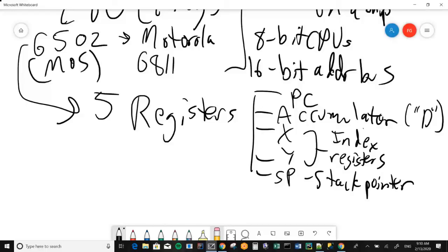When you did the jump saving the return address, it would take the value from the program counter and store it at the memory location referenced by the stack pointer. Then it would increment the stack pointer by 1, thus doing a push onto the stack, all in circuitry. So you think back to data structures where you coded up a stack. On the 6502, they coded a stack in hardware.